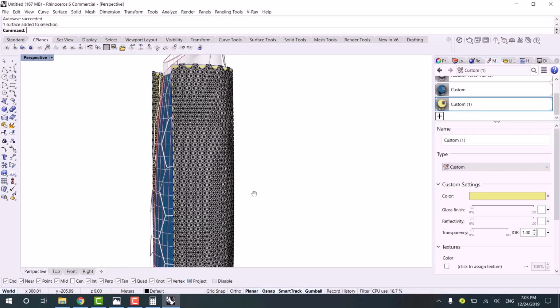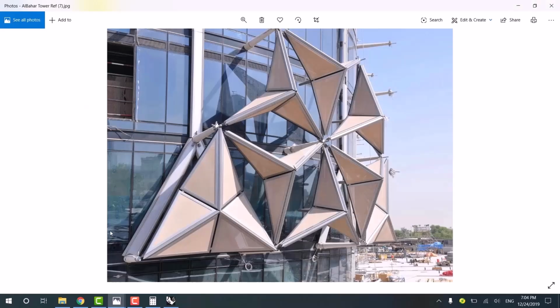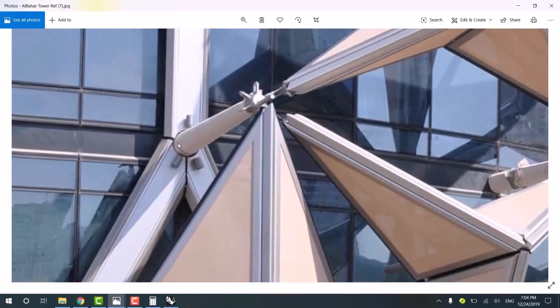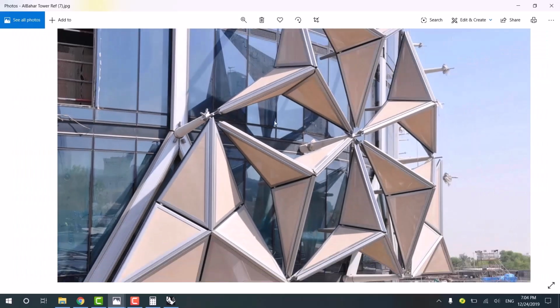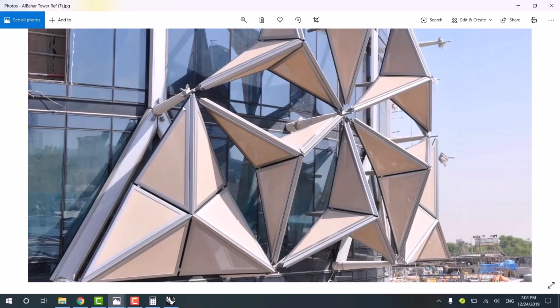Now you are able, with the use of the pictures that you have from the project, to take care of the details of your project. For example, you could pay attention to these objects, two circles in your first module. You could loft here, extrude it, and you could draw it and then use the array polar. Again, a curve, pipe, and keep going. And here, the more you care about the details, the more professional it would become.